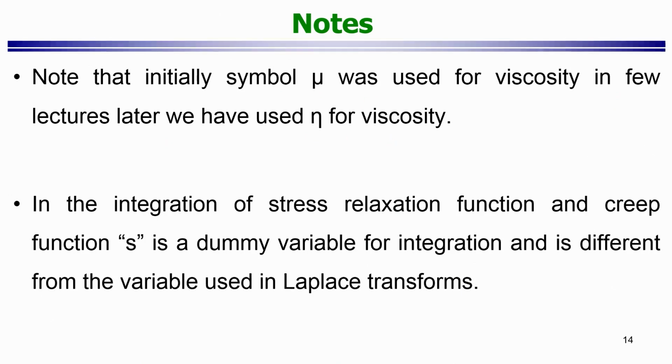In the integration of the stress relaxation function and the creep function, many times we have used s as a dummy variable for integrations, and the dummy variable s is used in the time sense. But it is different than the variable used in Laplace transforms. We used Laplace transforms to solve some of the equations, and there also an s appeared, but the two s's are different. One is in the Laplace domain and the other is in the time domain.